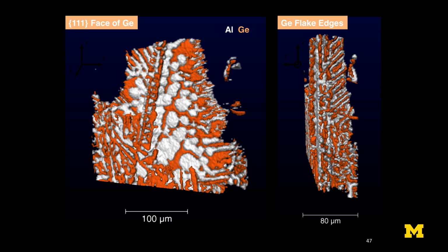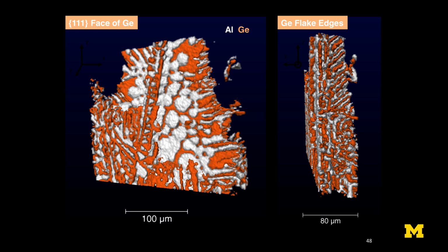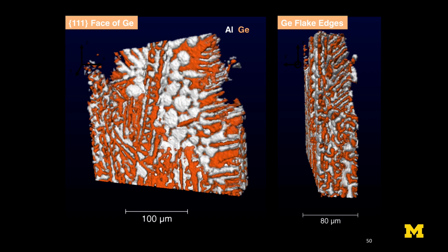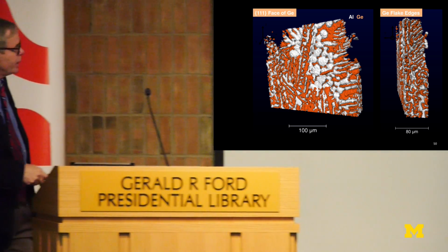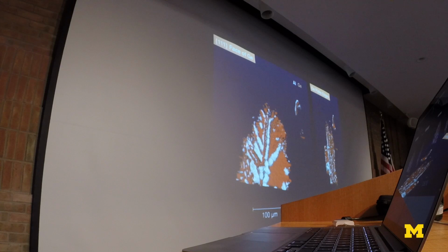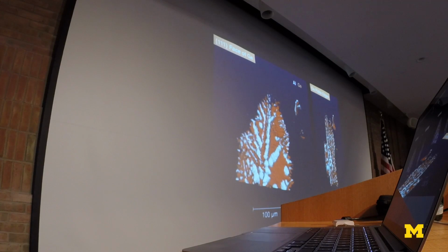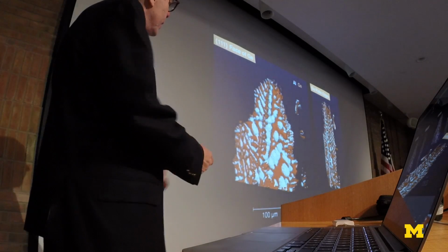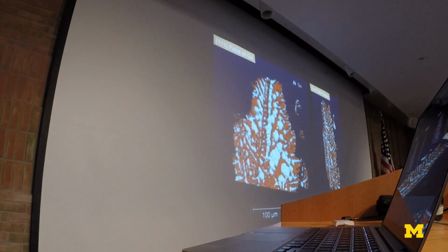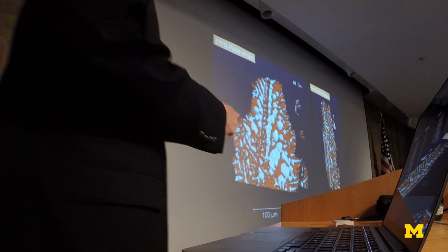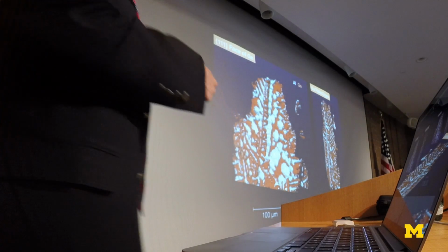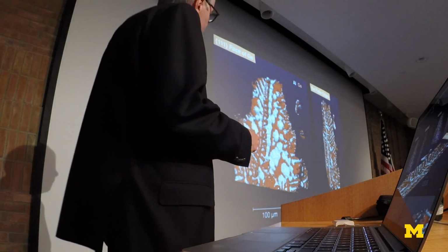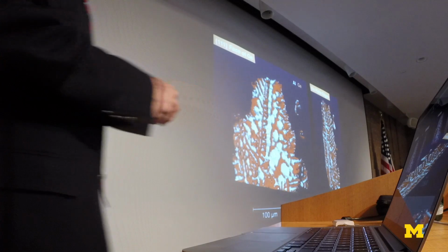And so you have a cooperative growth process, but where the aluminum is actually working its way through holes in the germanium plates. And so that's one example over here. There are other examples up here. We watch these things appear through the plates. And so there was a large controversy in the community back in the 70s, where people said that the way this eutectic grows is that it nucleates aluminum islands independently of the growth of the eutectic, and it's not cooperative growth at all.